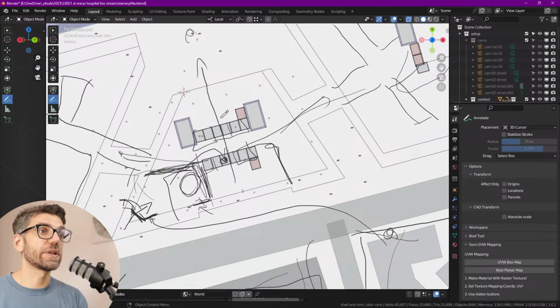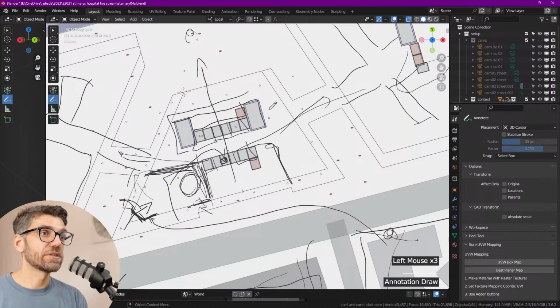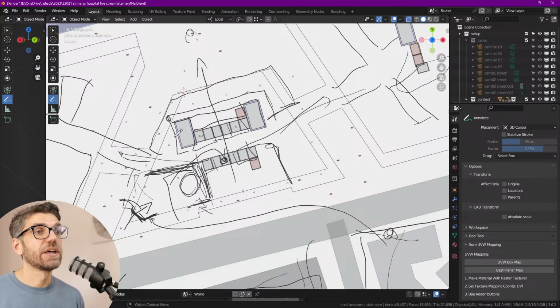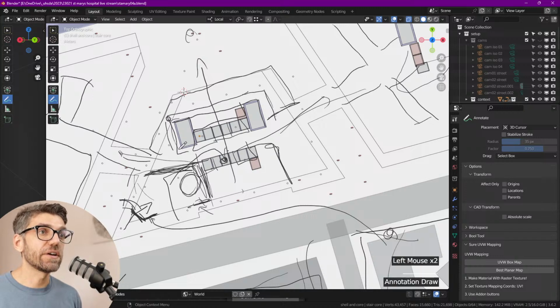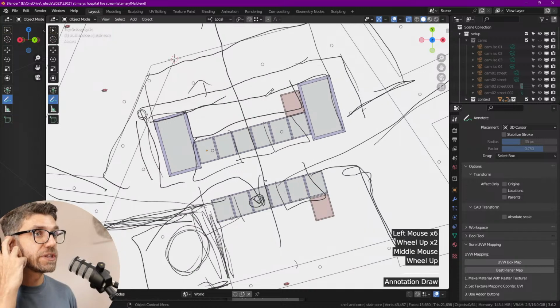So let's think about the circulation in these upper buildings. The most basic circulation would be, right? This is all wrapped up. That's some kind of core. So we've got a corridor that's doing this, right? So the corridor is coming through there. We have everything in these areas. That's the occupied space. This is a very tight, awkward corner. So you might need to lift everything up, but the situation will be exactly the same. That's the most efficient circulation, right? So you come into this area, you go around in here, and then either this whole thing is a suite of some sort, or you have rooms that are aligned into this edge over there.